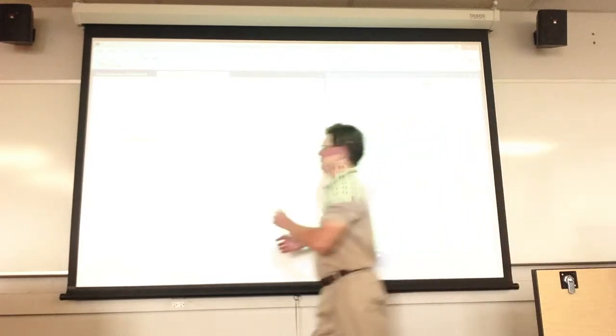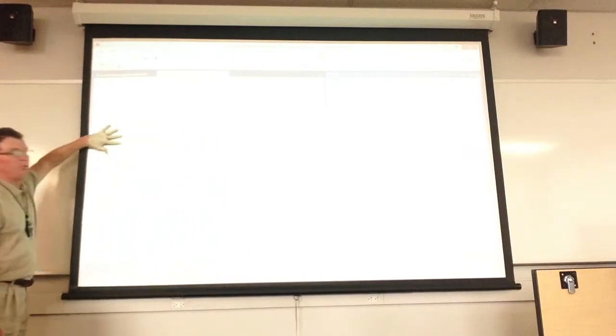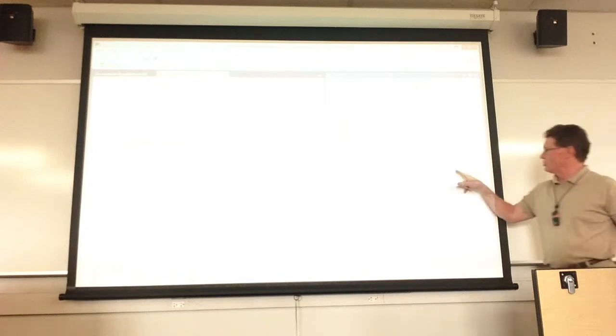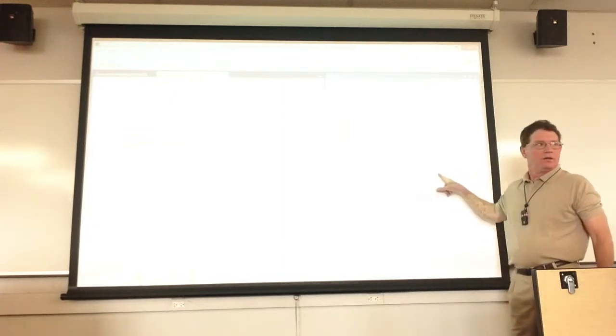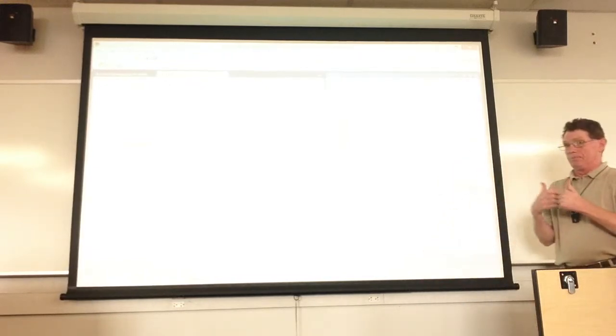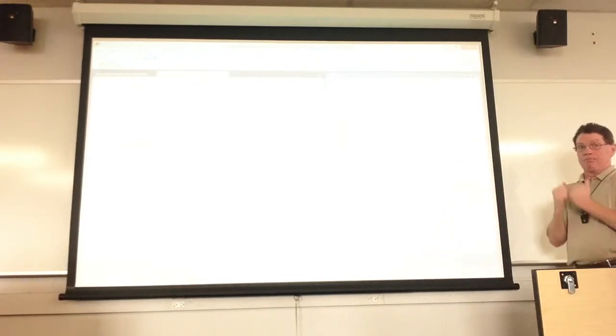All right, now what we're going to do is force, that's what this is going to do now. After I've written to it, I'm now going to force that port to be an input so I can read from it. So that's why I set up that R16 to have all zeros in it. So now we forced it, and you'll notice that all these are outlined in red. Okay, that means we've changed the status of those pins. They were changed from outputs to now inputs.